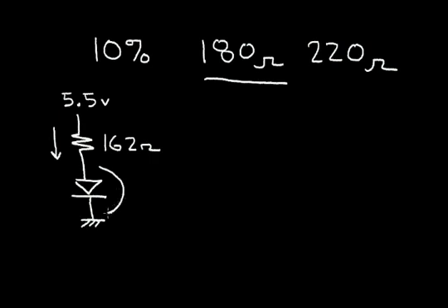and if I have the minimum possible drop across my LED, which I'm going to say is a little less than the 1.8 volts. I'm going to be a little safe, say that could be 1.5 volts. So under these conditions, that's the worst case for this maximum current. So let's see what the maximum current could be.